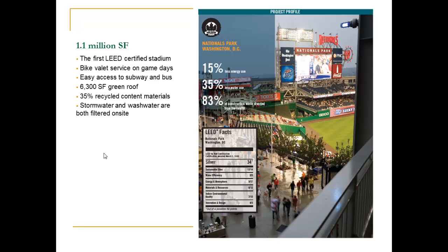One of the big things with LEED certification, and something that's very important nowadays, and especially on campus here, is stormwater management. If we have two spaces that are both 4 acres exactly, and one is grass and vegetated and the other one is asphalt, and we have a torrential rainstorm, which one's going to run off first into the Stillwater River? It would be, of course, the pavement.